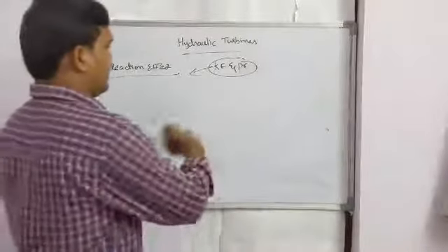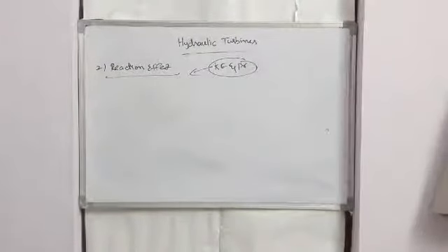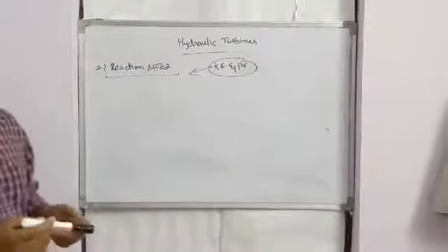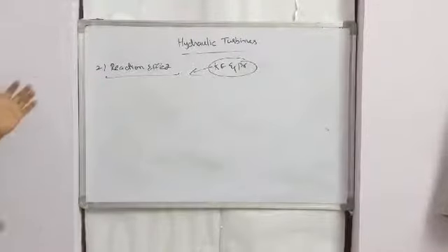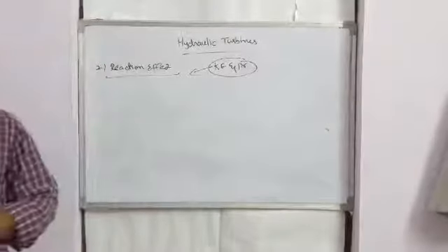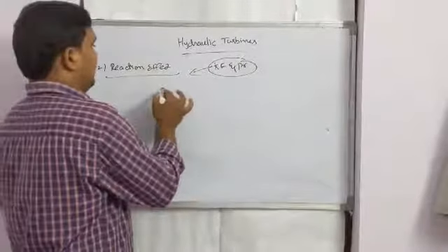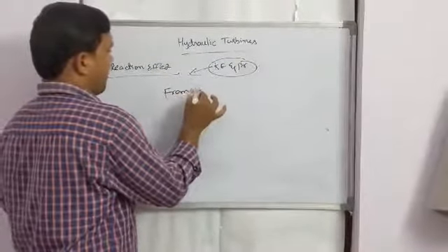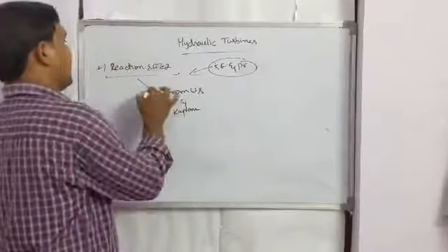The blades of a reaction turbine are closed, sealed from the atmosphere. I showed you earlier how the turbines are closed and sealed, like Francis and Kaplan. It is different from the Pelton wheel. We already discussed the animations of these turbines. The most successful and most used reaction turbines are the Francis and Kaplan turbines, and other types of reaction turbines are Fourneyron, Thomson and bulb turbines. In real-time examples, Francis and Kaplan are the most successful reaction turbines.